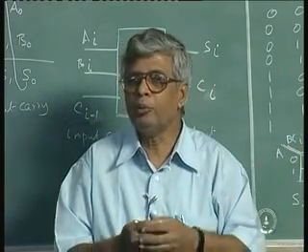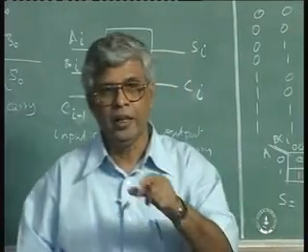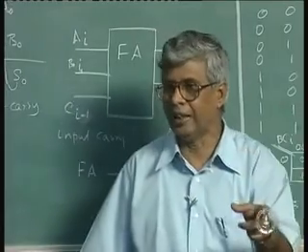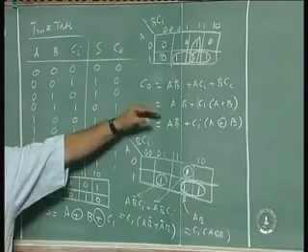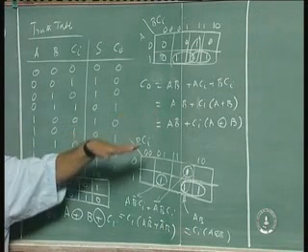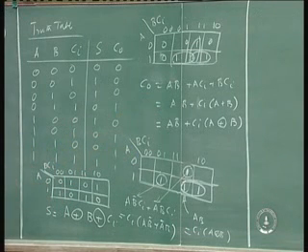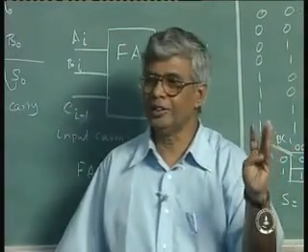Sometimes I may say give me the simplest possible solution, then in that case I have to go for an OR solution. Exclusive OR gate is definitely a more complex gate than a simple OR gate. So this is the philosophy of minimum sum of product expression. Minimum sum of product expression does not always give you the most optimum solution in terms of practicality. We saw it in the case of gray code converter.